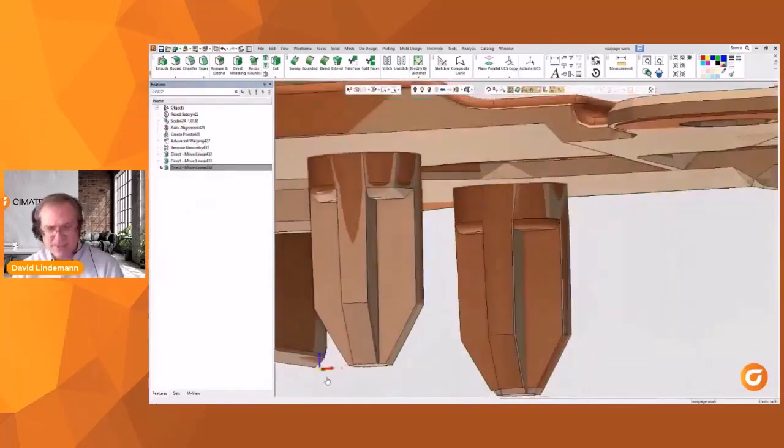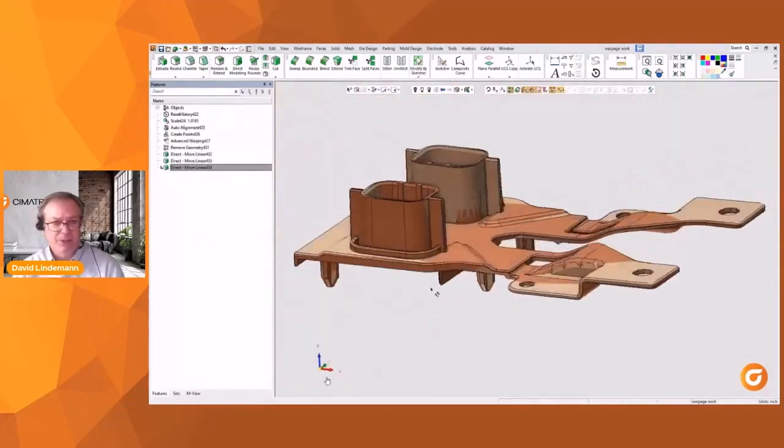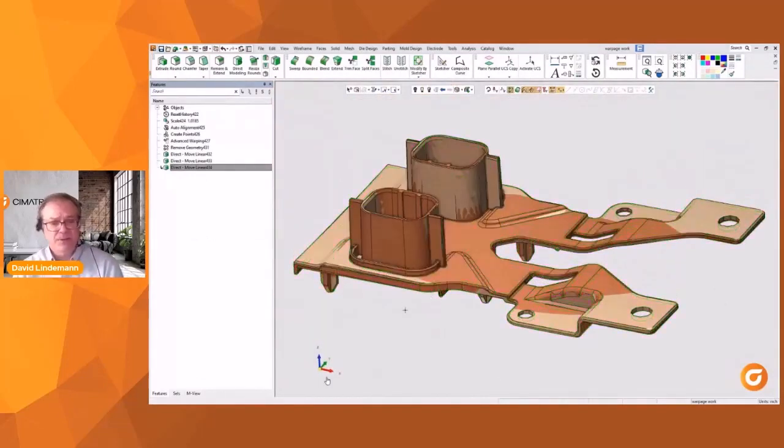So like we said, there's a lot that goes into dealing with warpage, and no two parts are the same, and there are different causes for the different warp conditions we measure, right? We like to know what those causes are so that we know how to attack the situation. But here, hopefully, you've seen some tools that greatly take down that workload, that we can look at the draft angle conditions and we can deal with those. Also, we can deal with all these different positions, the way the part may warp, and we can capture that, reverse that, now save that into a CAD file and make little tweaks along the way if we desire.